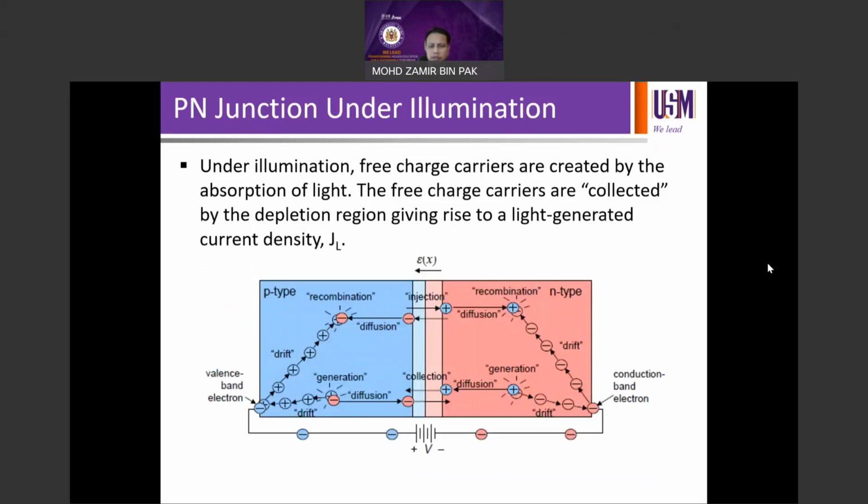We have also discussed last time about carrier injection, right? When we compared, the change will only be seen in the minority carrier but not in the majority carrier, because the majority will remain the same, especially when you're talking about low injection condition, right? And the condition will differ, of course, when you talk about high injection level.